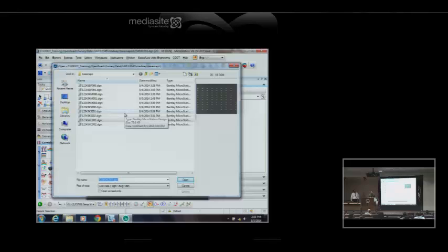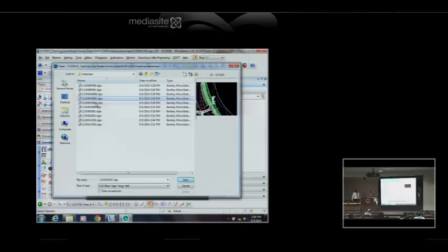So I've got a KM, which is new, there isn't a KM in the ODOT standards. Everything that was Geopack related had a K and an M for modeling. So I have a KM base map here, and I've got a 1 and a 2, and my intent was to lay out an alignment and throw in a template and do the side road, and obviously that's not going to happen. But I did split them out. So there's a corridor model for mainline, there's a separate file for the side road. And the answer from Bentley when that question was asked was always, do what makes sense for your project. If it's a really small project and it makes sense to put everything in one file, that's fine.